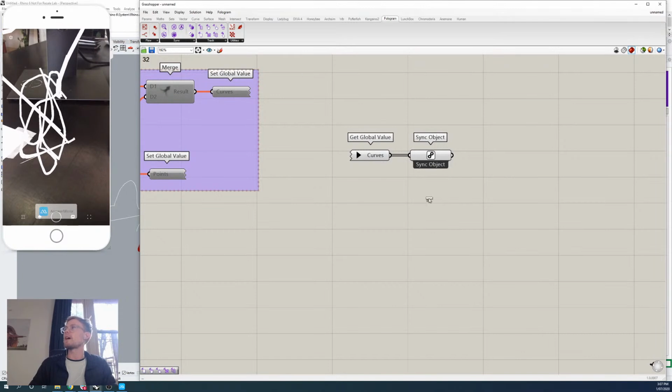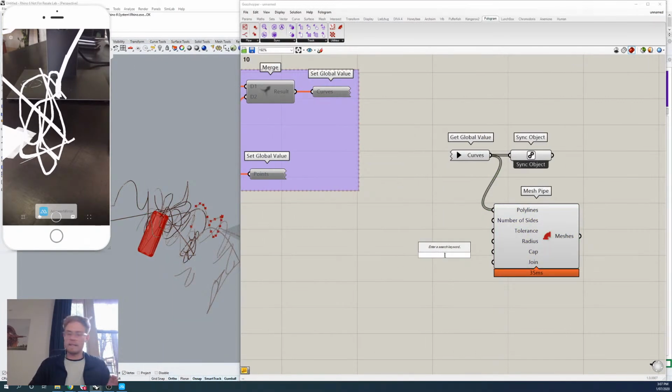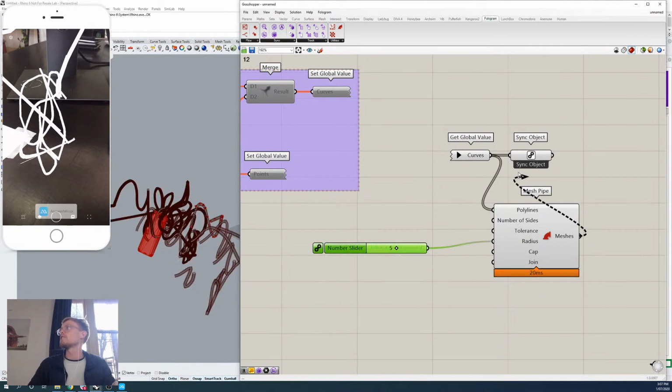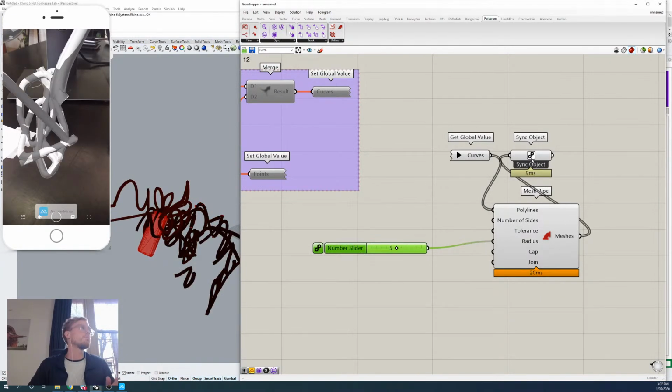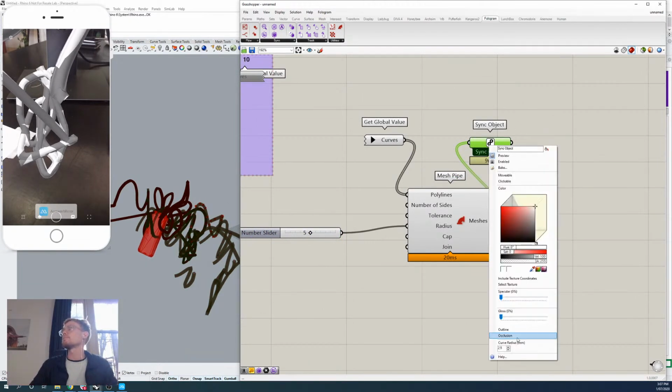One last thing that you could try that could maybe help you out is just change this curves output to a mesh pipe geometry like this. And maybe you could give it a radius of, I don't know, 5 or something. And then you could plug that in. It might be a little bug, or it might be a scale issue that you're having as well, like with the curve radius.